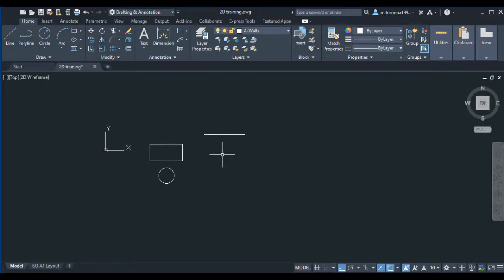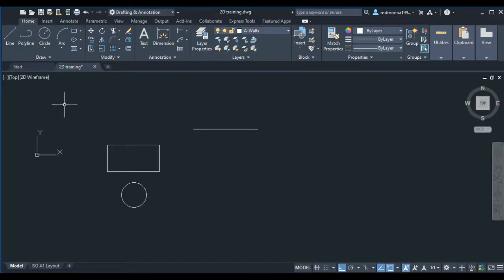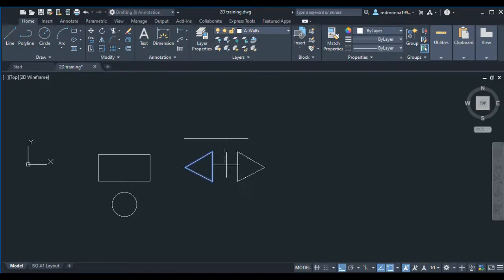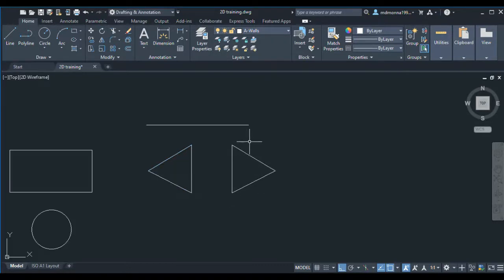Mirror means if we stand in front of a mirror, we can see our same face in the opposite direction. For easier understanding, I make one triangular shape here, so it is easy for us to understand the mirror tool. I select the triangle, choose the mirror tool, go vertically down, and you see I already made one mirrored shape.